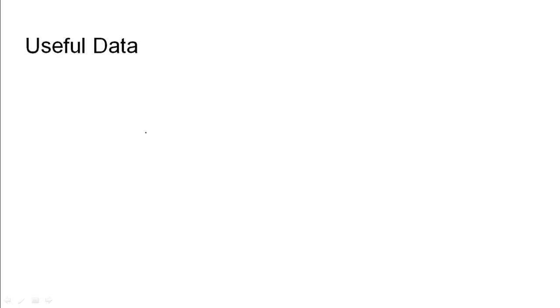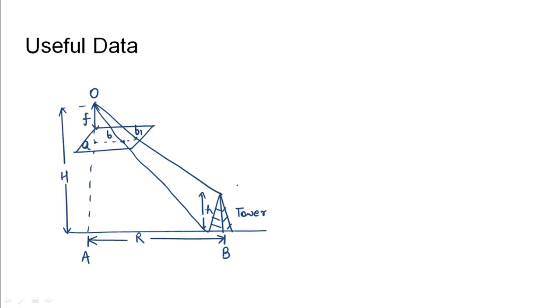Let us assume an aeroplane doing vertical photogrammetry. So the camera has been fixed in the aeroplane at point O, which takes a photo at focal length f of a ground surface AB, and the surface is projected on the photo as ab. But here, since the object is a vertical object of height h, that is a tower, it will have a certain displacement along the height of the tower.